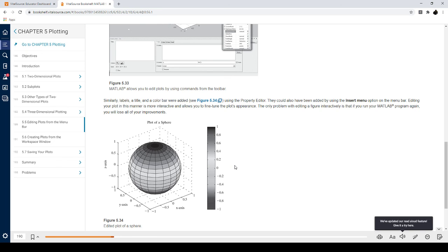It's over the factor of safety of 1.5 or whatever, which means that it could hold 1.5 times the amount that you put on it. And if there's anywhere that's red, it means that it's below that, which means that it will fail when putting on that load. And so that means you have to add more material or change the shape at that spot.